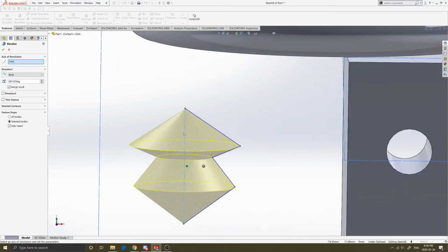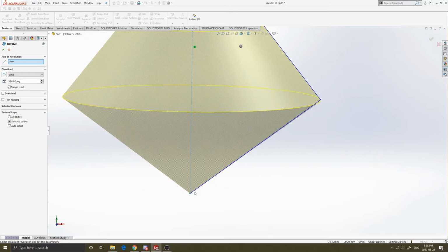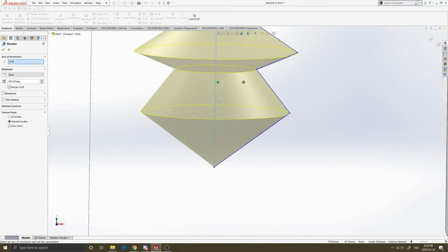As you can see, it worked for some reason. I think it's because the computer recognizes that the center point, these exact coordinates, there's already something there, or you're revolving right on top of it, so it doesn't really define it. I don't know. Your guess is as good as mine, but I just know that you can't enclose this, so you must have an open border. But these points must actually meet this axis of revolution.